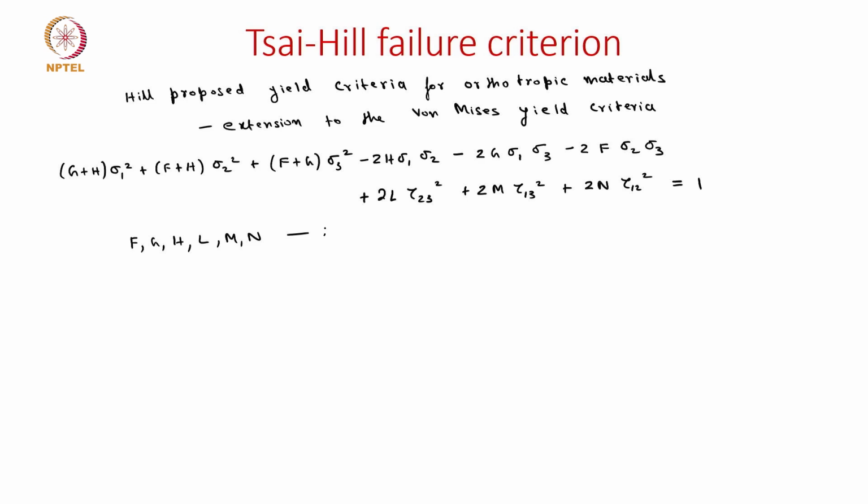These are the failure strengths, written in terms of the fundamental failure strengths, again X, Y, and S. So mind you, here we are not differentiating between tension and compression. We'll talk in a while why we are simply writing it as X and Y instead of with the subscript.